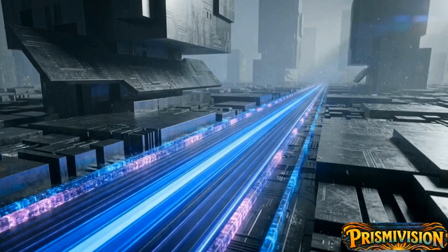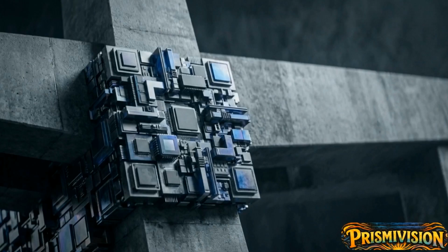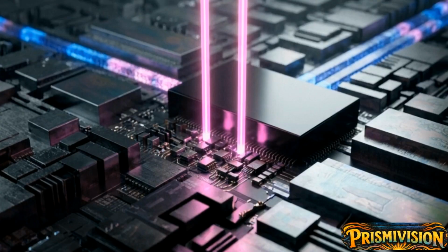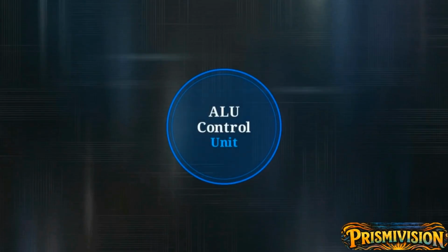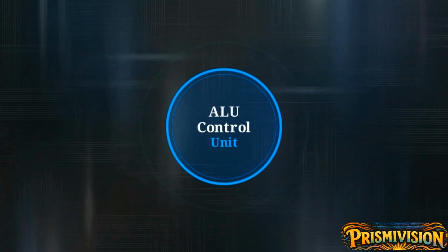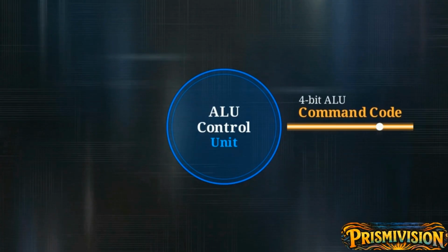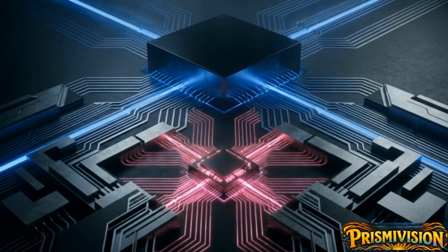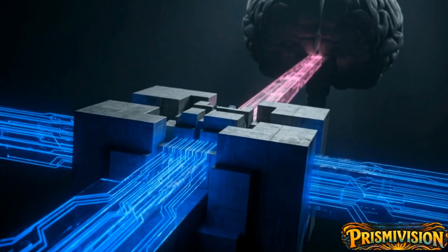While the main control handles the broad pathways, it delegates the precise mathematical instructions to a smaller, localized control unit positioned right next to the ALU. The main brain does not send the entire command. It only transmits a basic, high-level 2-bit signal to this secondary unit. That localized ALU control then merges that 2-bit signal with the instruction's unique formatting fields, generating a highly precise 4-bit operational code specifically for the ALU. This multi-level delegation keeps the processor fast. The heavy-lifting data path gets the precise, detailed commands it needs without bottlenecking the main control unit in the process.